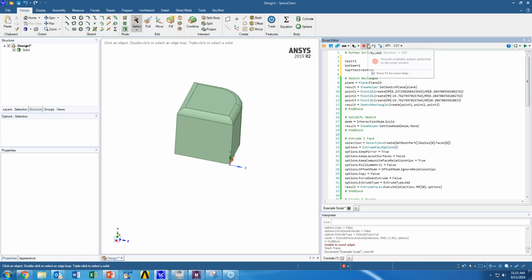And then from a top level best practice, I've found in using the SpaceClaim scripting, my most robust behavior generally comes when I'm set under the record dropdown to verbose mode, as well as index mode. Essentially, really I'm going to talk about smart variable and index.